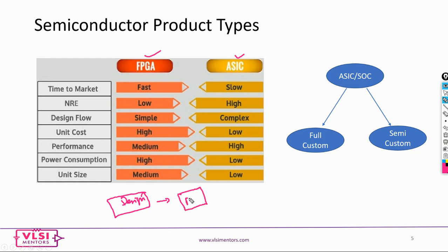So what do we do? FPGA is a kind of generic chip on which you can program. Basically, you can program those FPGAs, field programmable gate arrays. The chip is already available, like any microprocessor or microcontroller. You can just buy it, do synthesis, and then program your FPGA. And the non-recurring cost, basically the initial investment and things like that, are all advantages if you use FPGA.